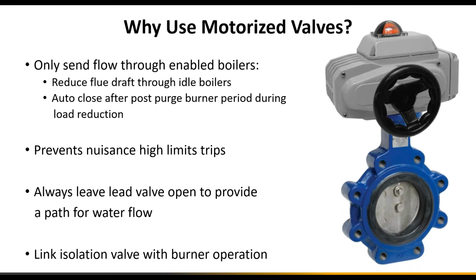Of course, we always want to make sure there's at least one of these open, otherwise the main system pump would be deadheading. The overall operation of the motorized valve is typically programmable, where you can have it remain open for a certain amount of time, or have it auto close after the burner shuts off. Its functioning is fully programmable. On larger systems, you can set it up where you always want at least 2 boilers on, so you can have a min open of 2, and then have the system bring on additional boilers as necessary.